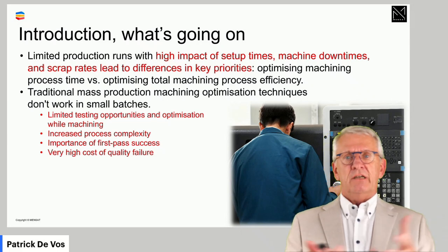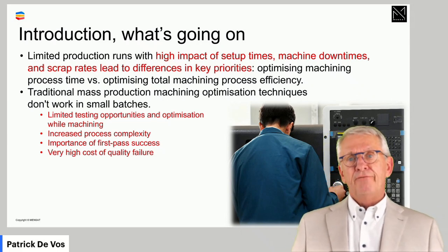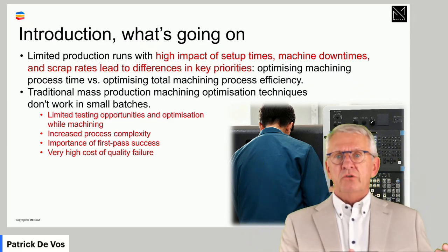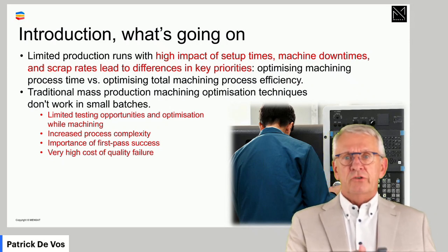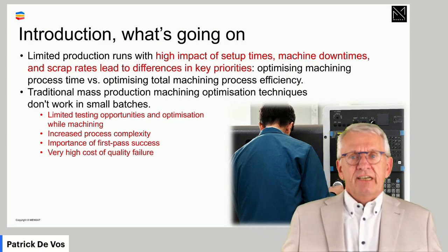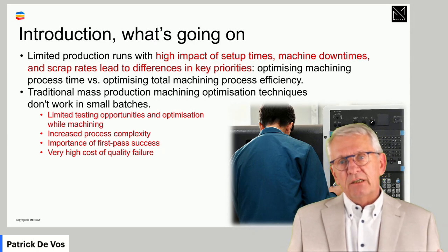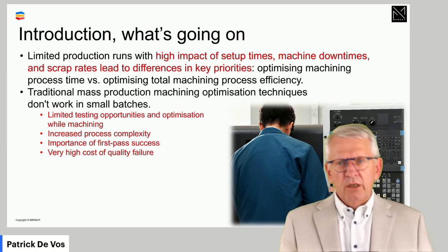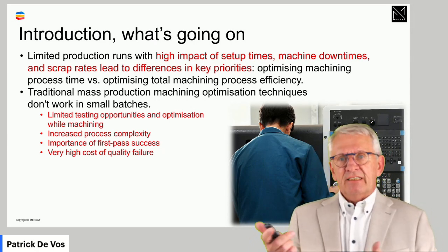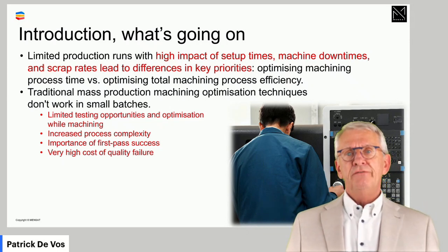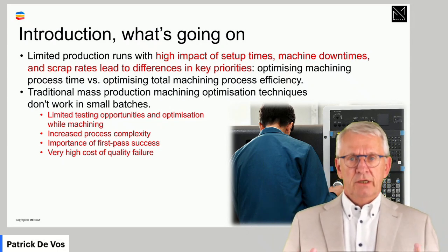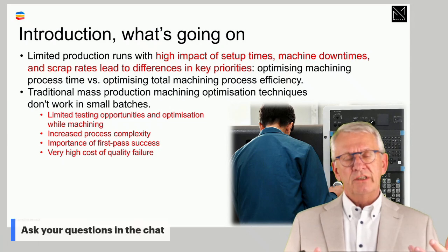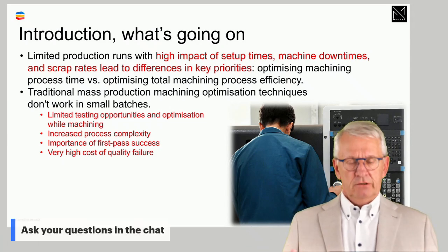Well, you take some technical experts, you take a fortune of testing tools, you go to the machine, you take a couple of hundred of workpieces you are allowed to destroy, and you start testing in a practical way. A little bit more, a little bit less, a little bit this, a little bit that, and in the end, you find the ideal set of cutting conditions. That's how we do it in mass production. That's how we've done it since ever.